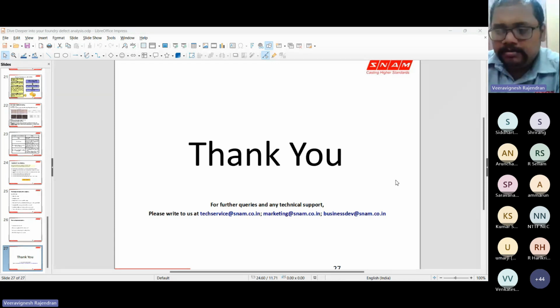And if you are able to highlight on which particular days you are having the problem, if you're able to relate it to the already measured parameters which are available, say pouring temperature, filling time, and ingredients of the mold like coal dust, bentonite, moisture content, AFS number of the sand, whatever test you have already done, for which you already have the data, and you try to correlate with the data available, then I think you have got a clue inside the process. For every defect, the process has a clue.